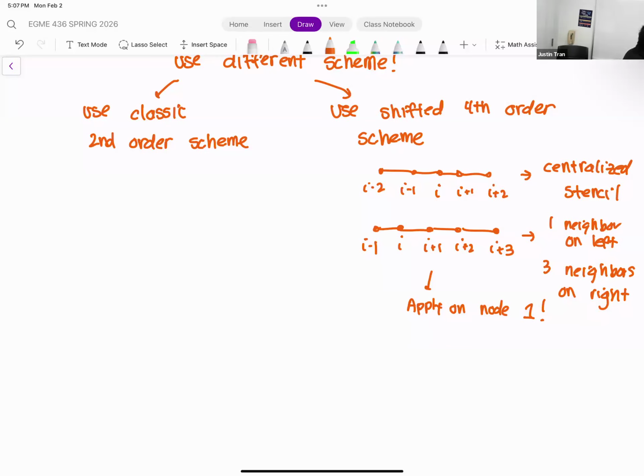Yeah. So typically, if you are going to change the order, you have to rewrite your code, which some people are into, but 99% of people are not. And so the way to achieve better accuracy for most people is just to refine your grid. Even with second order accurate, we know that our accuracy improves with delta x squared, right? And so probably the easiest way to improve your accuracy is just to make delta x small. That means your mesh is going to be bigger, which of course increases your computational costs. But that's usually a cost that people are willing to pay.